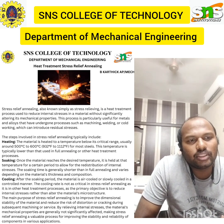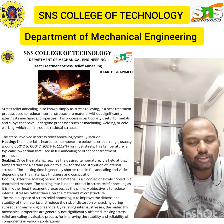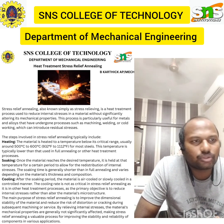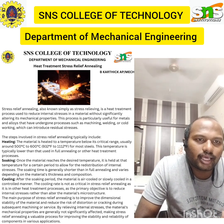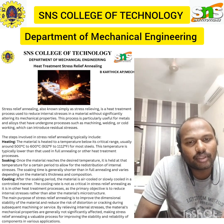The second step is soaking. Once the material reaches the desired temperature, it is held at that temperature for a period of time. The soaking period allows the material to relax. That means the soaking period allows the internal stress to gradually redistribute and relax, leading to a more uniform stress distribution within the material.